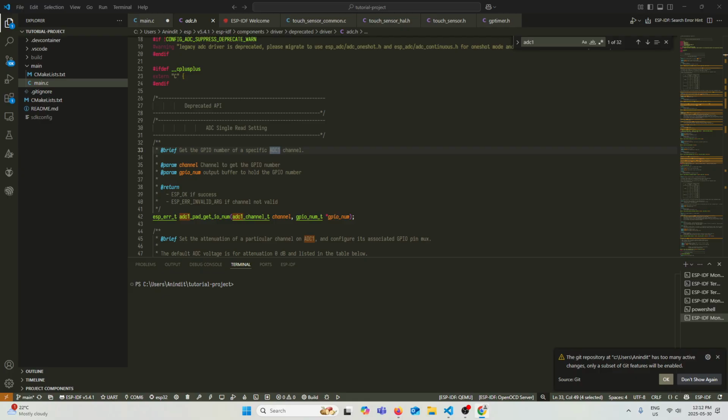Let me configure this. We must first change... Probably use longer wires for this. So first, 3.3 volts. Let's connect that to this one, right? And then we'll analyze from the middle. Okay, this is good. Let's go to pin 26, GPIO 26.